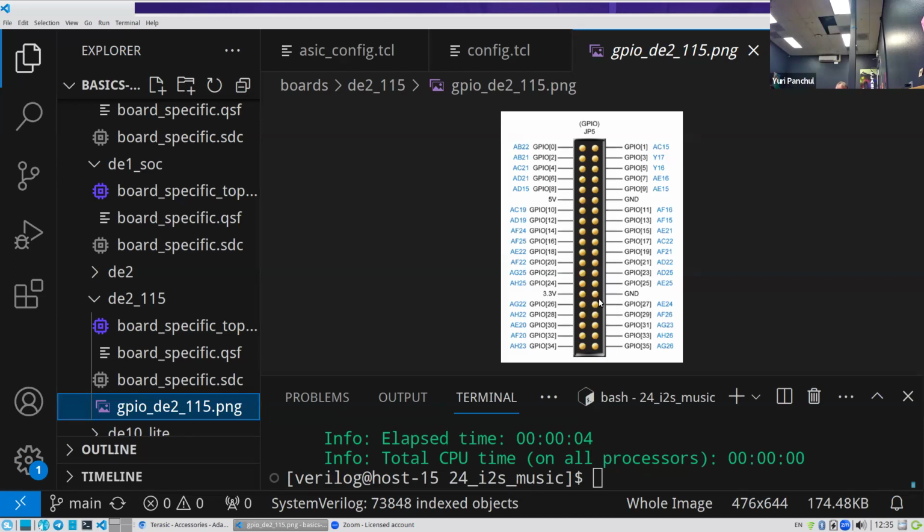Okay, so you're using Xilinx boards. Same power supply, right? Same 5 volt, yes, the same. So the voltage is the same. But you need to connect this one, which has 2 leads, right? Let's see which one. This one is for USB power, and this one is for something else. Connect it here. First try this simple example to see whether it works.